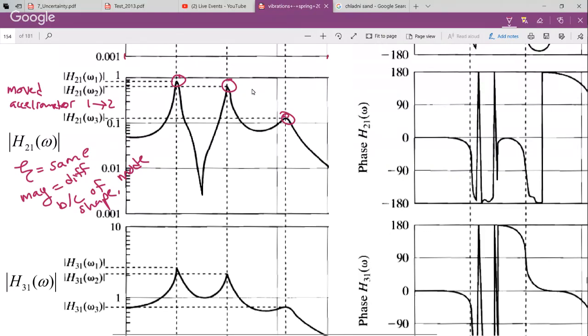We didn't go down that path. We could have, but I haven't in years in the undergraduate class. Once you get to your frequency response equations from your models, if you set your driving frequency equal to your natural frequency, everything simplifies significantly and you get two useful equations. The first is the estimate equation for zeta, which is an estimate because you're still taking it from data. The other is one I haven't shown you yet, which we're going to use to extract mode shapes. My point is you don't even need that to appreciate what this data provides.